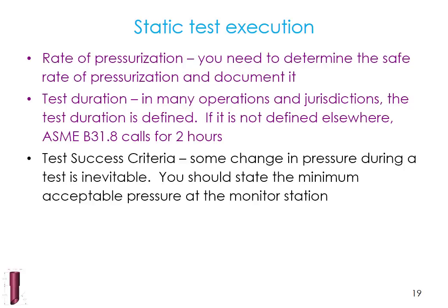I don't know if I add a little bit of water, whether what I added was a little bit of water or a lot of water. So basically what I say is the operator can drain fluid out if pressure is increasing, but they can't add fluid if pressure is decreasing. So when I say that, I have to say, how low can it go before the test fails?